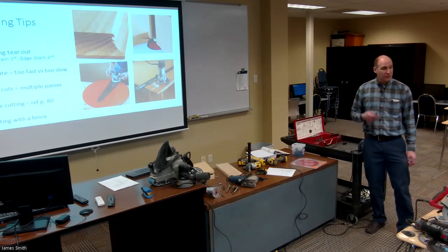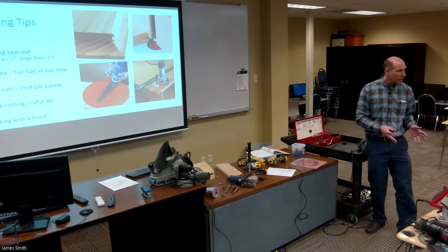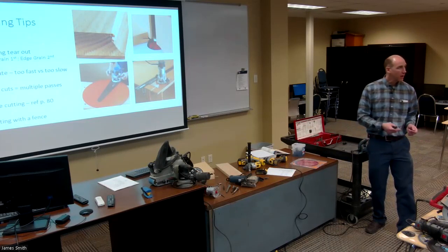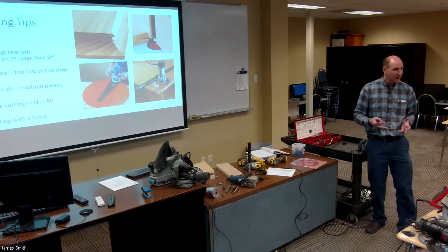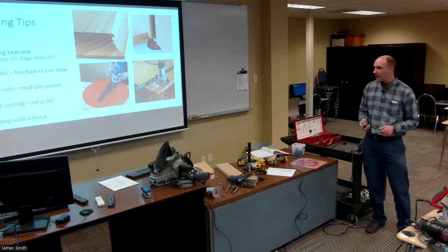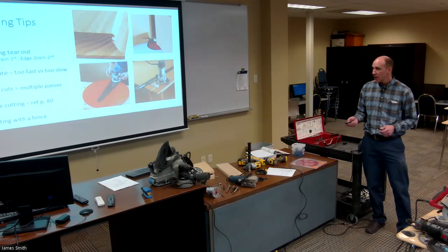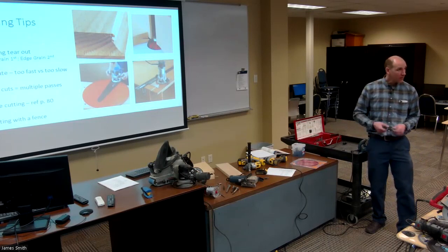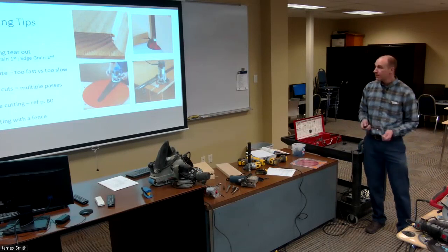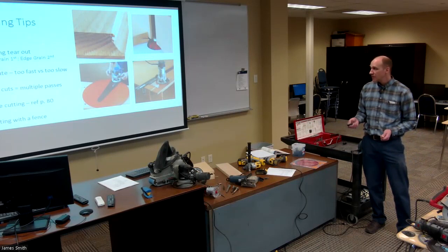With regards to feed rate, if you go too slow, you get a lot of burning, okay? If you go too fast, you get a lot of tear out. So you kind of have to find that happy place, okay? And so just be aware, if you're getting burning, go faster, okay? I think that's something that maybe people don't realize.